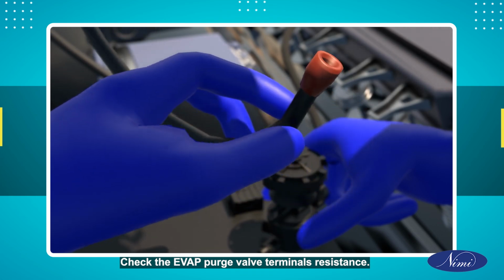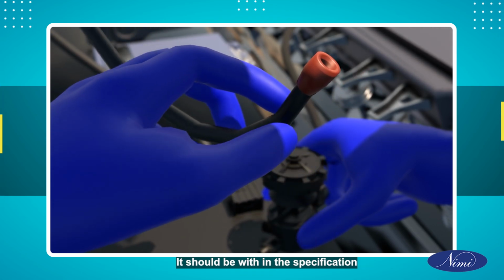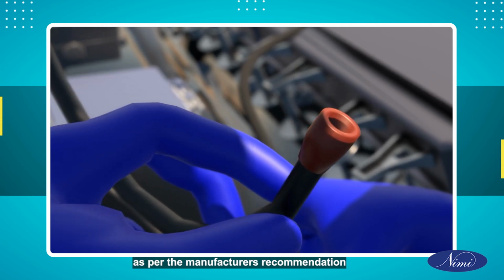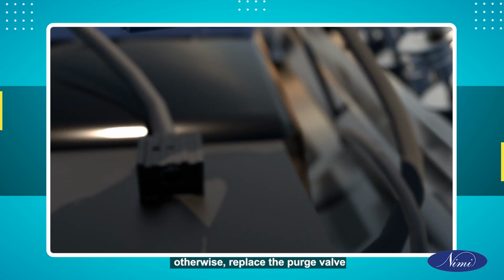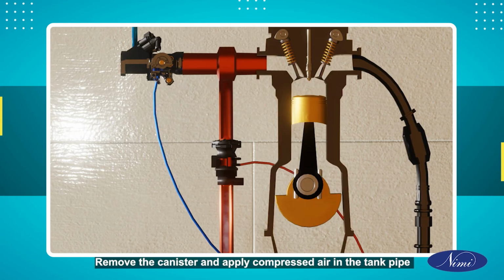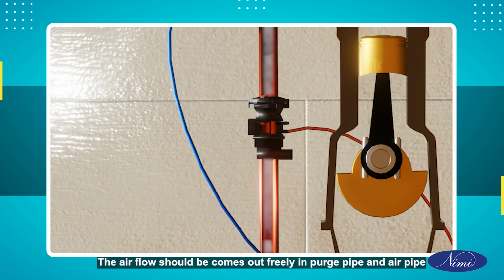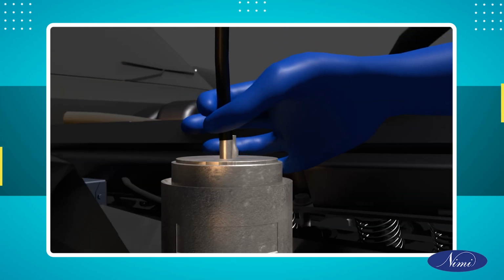Check the EVAP purge valve terminal's resistance. It should be within the specification as per the manufacturer's recommendation. Otherwise, replace the purge valve. Remove the canister and apply compressed air in the tank pipe. The airflow should come out freely in the purge pipe and air pipe. If not, replace the canister.